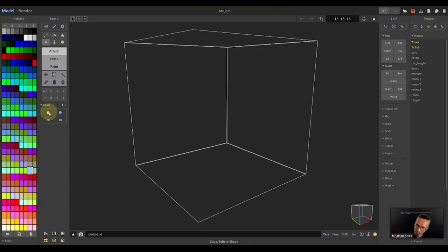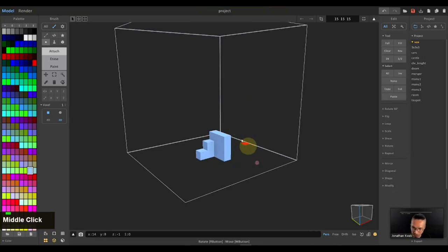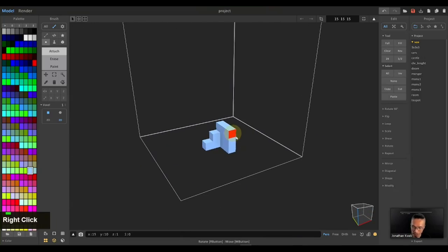In voxel mode, there are 2 options for you down here. You have the 2D mode and the 3D mode. We'll go through what they basically do. If you use the 2D mode and you click into the scene, you add a voxel. If you mouse over one of the sides of this cube and click again, you add a voxel in that direction. So you can easily add and create shapes in this 3D scene using this style. Very easy stuff.